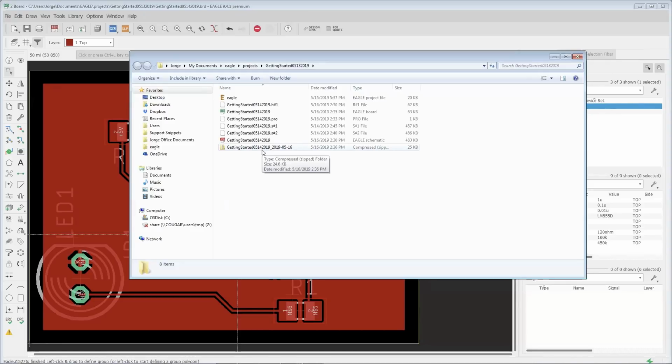And there we are. And there's our manufacturing data. It's that simple. Now, one thing you always want to do before you send off a board to manufacturer is to double check the Gerbers, okay? It is important to do so because in the end, the responsibility lies with the designer to make sure their manufacturing data is correct. So if you send them bad data and the board house processes it and gives you bad boards, you may be upset that they didn't tell you anything, but the responsibility ultimately lies with the designer to provide proper manufacturing data.